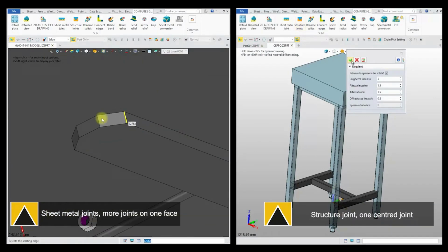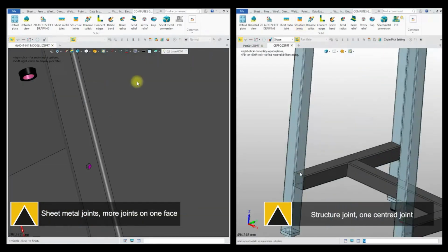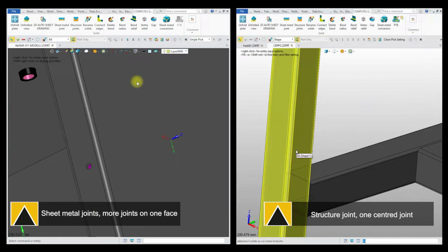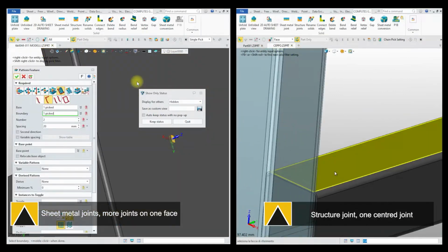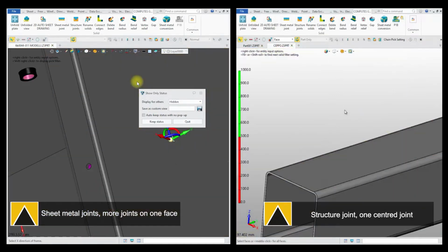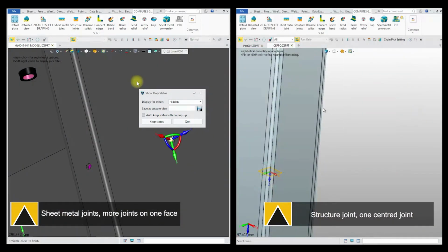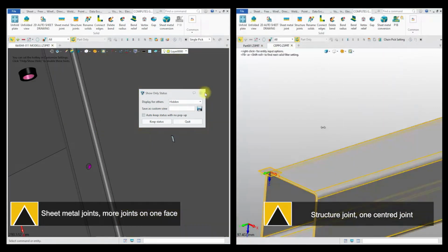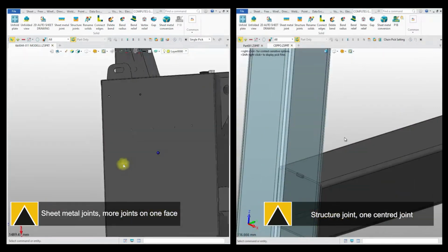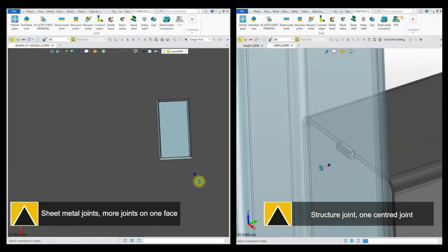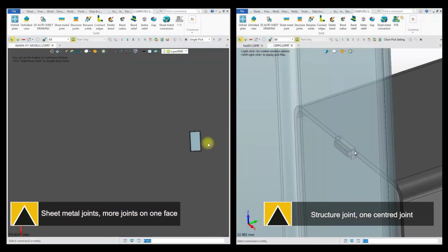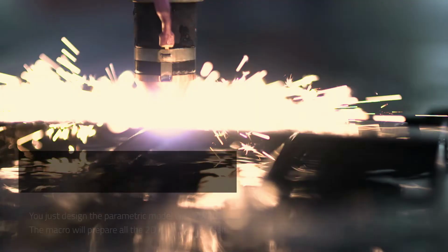User must type in also the number of joints and the distance of the first one from the selected edge, and the user can choose to have a certain distance from the starting edge and the arriving edge. How to use: compile the form with requested values, then select the male solid, the female solid, and the reference face of the male one. In case you are using multiple joint, you must select also the starting edge.